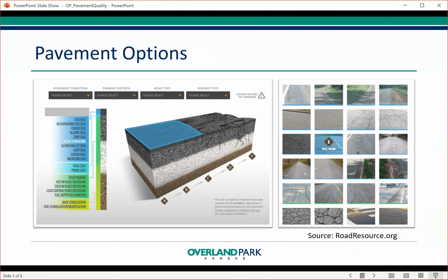The need to keep a uniform solid pavement surface promotes the use of pavement preservation techniques. As cracks begin to occur on an excellent rating pavement, the use of crack sealing prevents further infiltration of water, which accelerates the failure of the pavement. With the loss of a solid top layer, surface treatments like chip seal and microsurfacing create a protective barrier and improve friction to reduce vehicle sliding. While pavement remains in excellent condition and very good ratings, these methods will increase the life of the pavement to over 50 years. If the pavement deteriorates further, it begins breaking down the layers that make up the system.